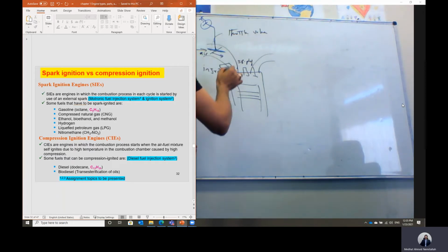Then the electronic control unit measures the amount of air based on the angle rotated by the throttle valve. Then it decides the time during which it will supply current to the solenoid injector to supply the fuel. As this time is elongated, more fuel can be injected. If we need less fuel, the time during which the electric current is supplied to the fuel injector will be reduced. Then, once the intake valve opens, we have fuel plus air.